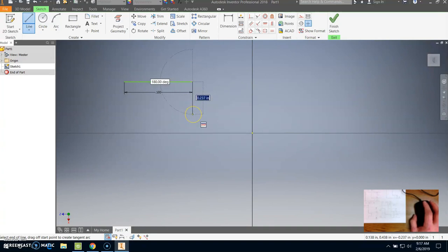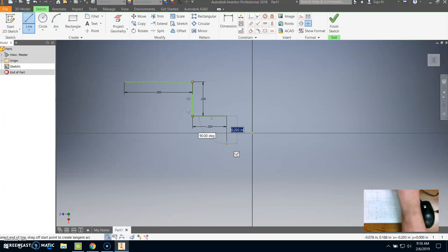Next thing I'm going to do is aim my line so it's the correct direction. This one I want vertical. And then I'm going to type in my correct measurement and press Enter. So in this case, since we're doing all of these little steps right here, those are all 0.25, 1/4 of an inch. So 0.25, I press Enter, and then I keep going. Aim my line, type in the measurement, press Enter. Again, I'm not clicking. All I'm doing is aiming and then typing in the measurement.